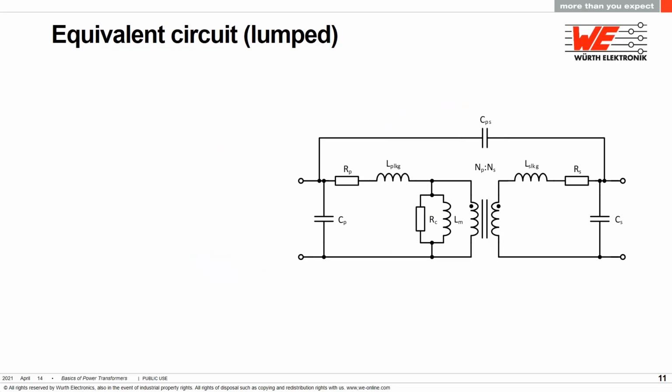Here is a basic lumped element equivalent circuit of a transformer. We're trying to show the basic features that would be involved in an equivalent circuit without getting into any great detail about each element. First, we split out the windings and apply the turns ratio to the perfect transformer. The nomenclature for turns is capital N subscript P or S for the individual windings. The ratio is written with a small letter n, such as n:1 or 1:n. There's no standard as to which winding is a reference, but typically you'll find the winding with the fewest turns is the reference. In a step-down transformer, the secondary would be 1. In a step-up, the primary would be 1. Just be careful when you're reading the literature.